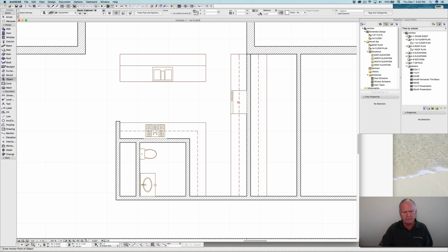And now we see that it's a little small. Maybe it could be a little larger, maybe if we had it 18 inches off of center here. The easy thing to do there is just hit the shift key, click on that, go to the back hot button, drag it up until you see that pencil turn black, and we're at the center of the toilet. And that distance is 5'6". If we want to be 1'6" less than that, that'd be 4 feet. So we'll just type in 4, enter, and we've got a cabinet there.